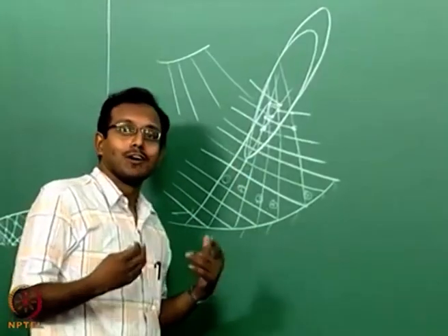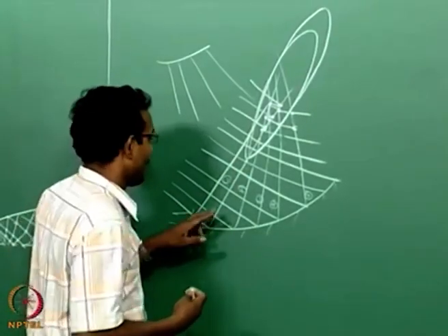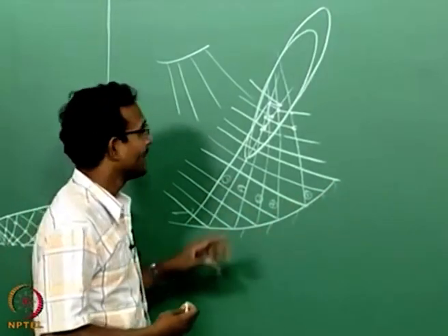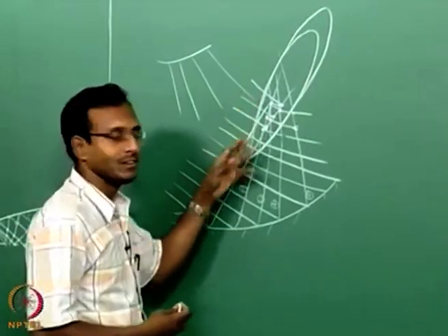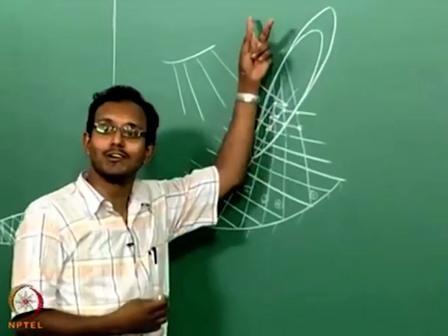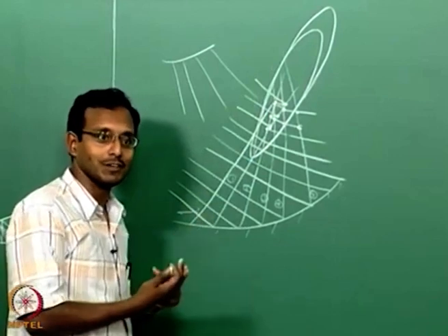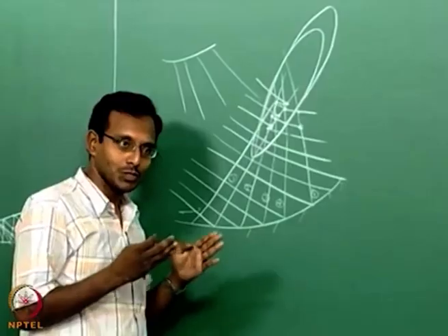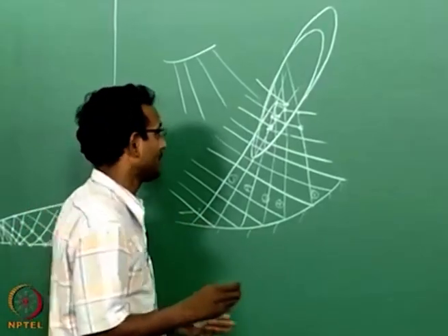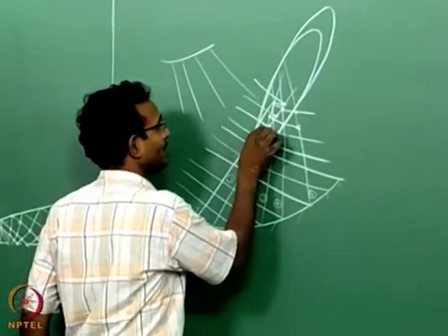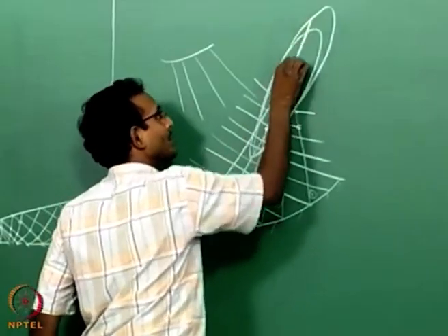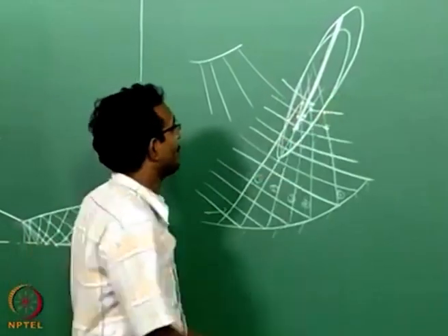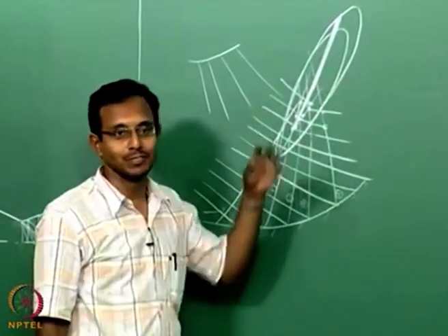What is our common logic from our gas dynamics? When compression waves come together, they form a shock, right? But here we did not do anything about that. We just let the compression waves cross each other and go, which is never the case. When compression waves come together, they cannot ever cross. The second wave cannot cross the first wave. They just both club together and become a stronger wave. That is all it can do. So all I have to do is just replace this whole region by one shock, which will take care of the flow field before and after this whole situation.